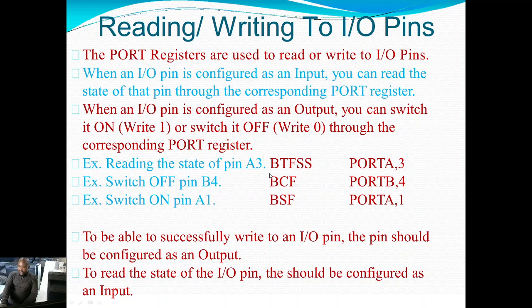For all of these instructions, because you are accessing the port registers, regardless of which port it is, both PORTA and PORTB are in bank 0. So these instructions should be executed while you are in bank 0.